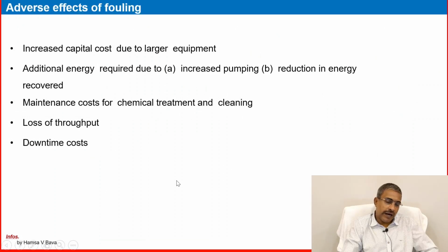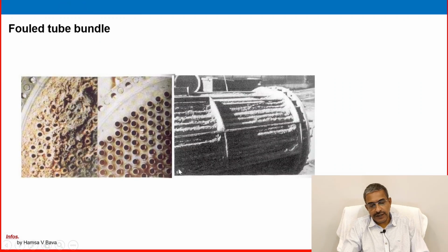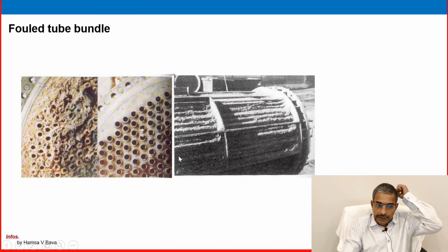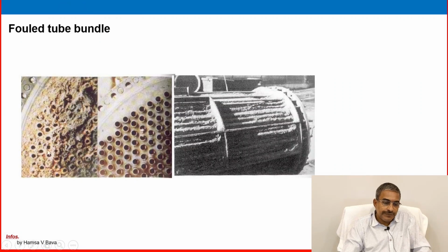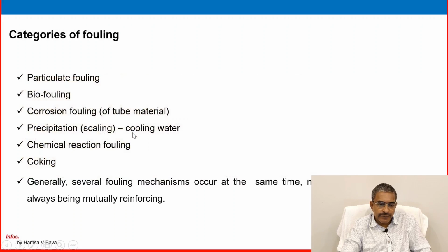So, the adverse effects of fouling: increased capital cost due to larger equipment, additional energy required due to increased pumping or a reduction in energy recovered, maintenance cost of chemical treatment and cleaning, loss of throughput, and downtime cost. These are the adverse effects of fouling. And these are two simple photos of a fouled tube bundle.